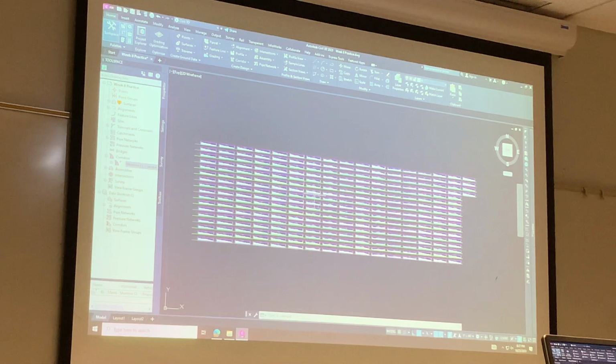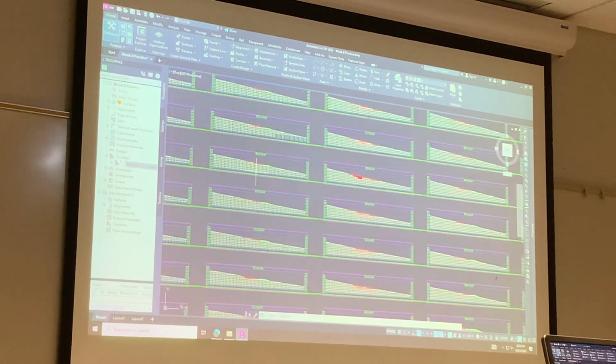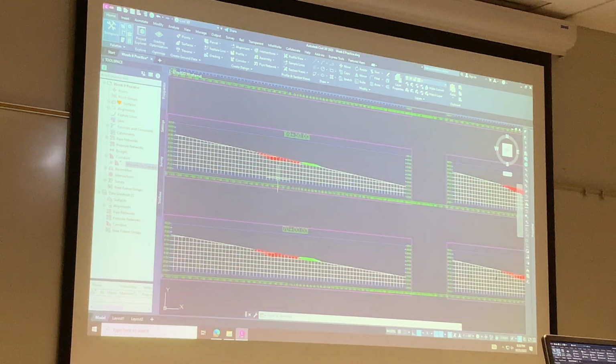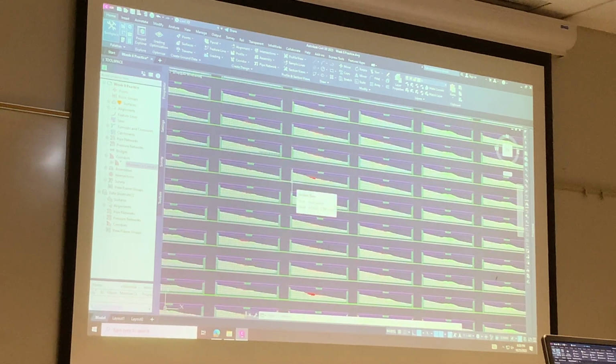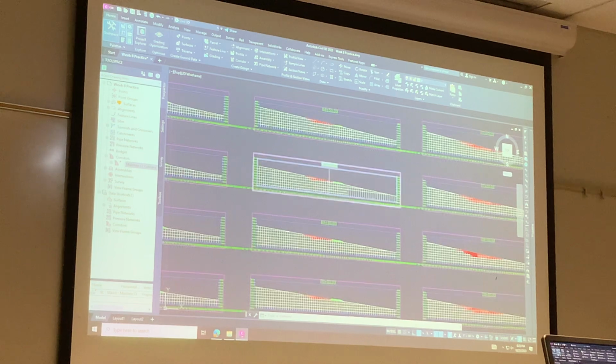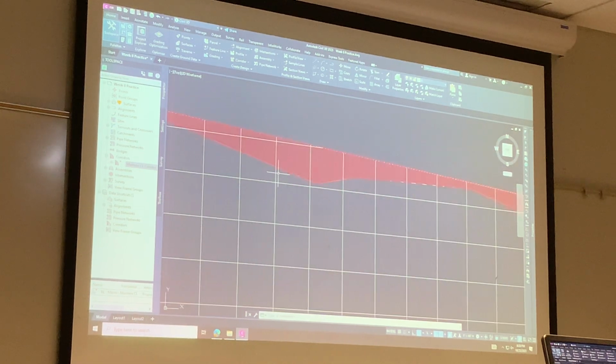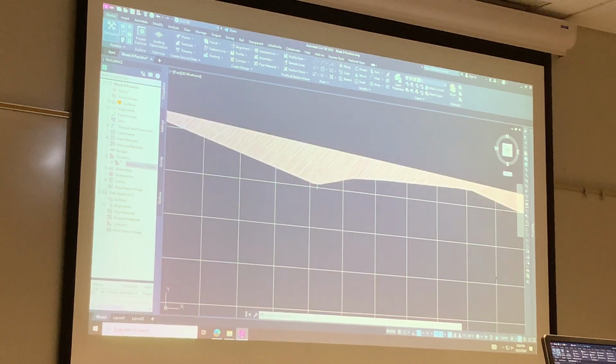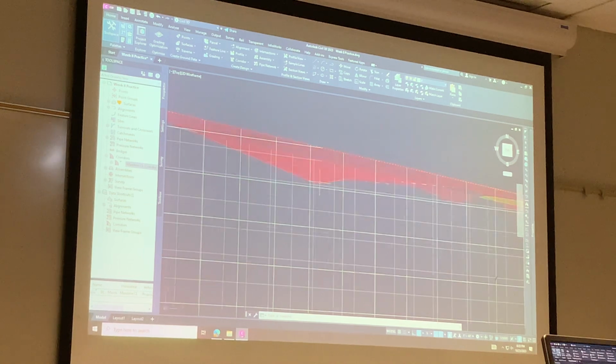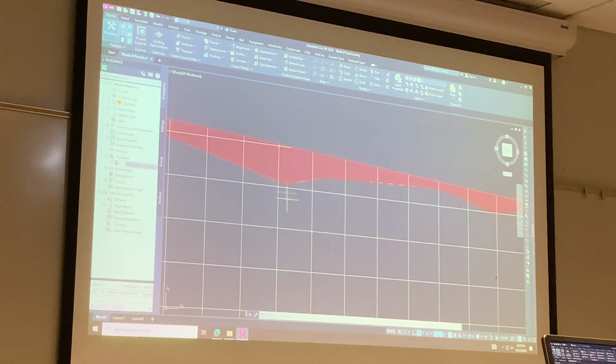So is this how they make sure they're not going off level, basically? You mean they being the contractor? Yeah, to make sure they're not going too high or whatever. Yeah, it's used for reference for them. Say, hey, at this station, you should be doing close to 10 feet of cut here at the end of the shoulder.